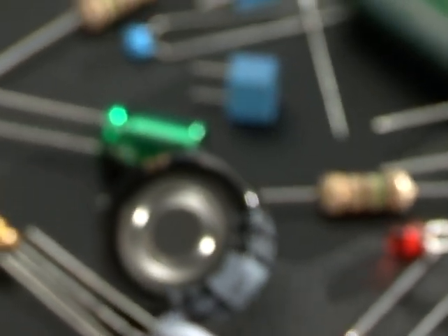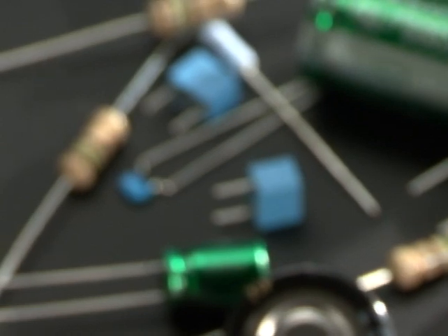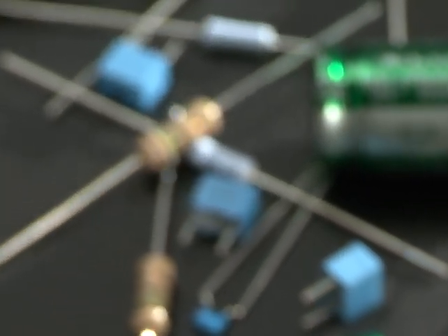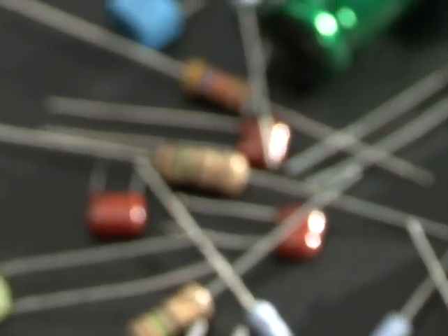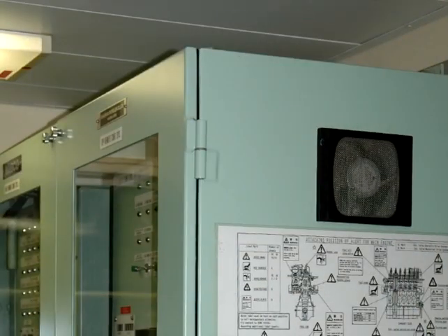Including the inverter for motor control, most power converters use a number of electrolytic capacitors. The life of these electrolytic capacitors is short, and they deteriorate more rapidly than other electronic components used in power conversion devices. Therefore, it is no exaggeration to say that the useful life of a power converter depends upon the lifespan of the electrolytic capacitors inside it.